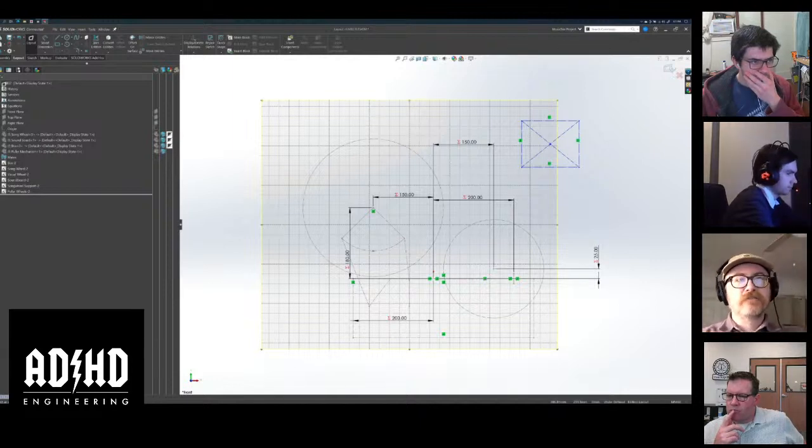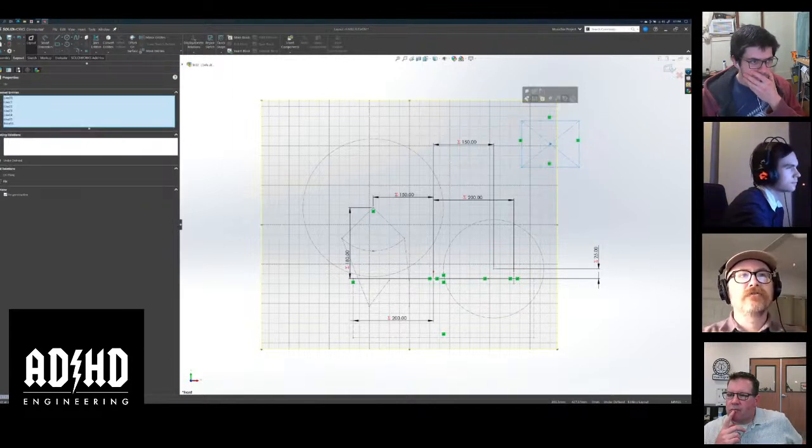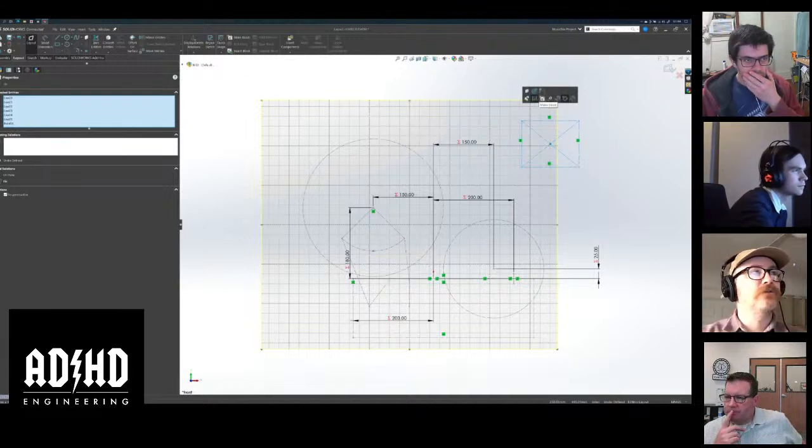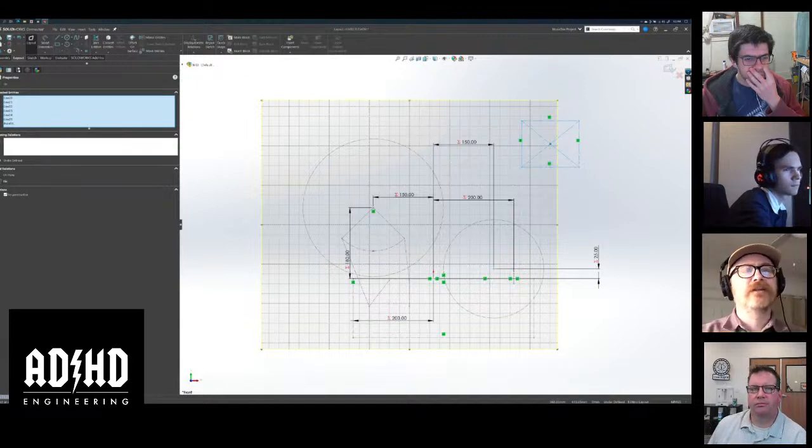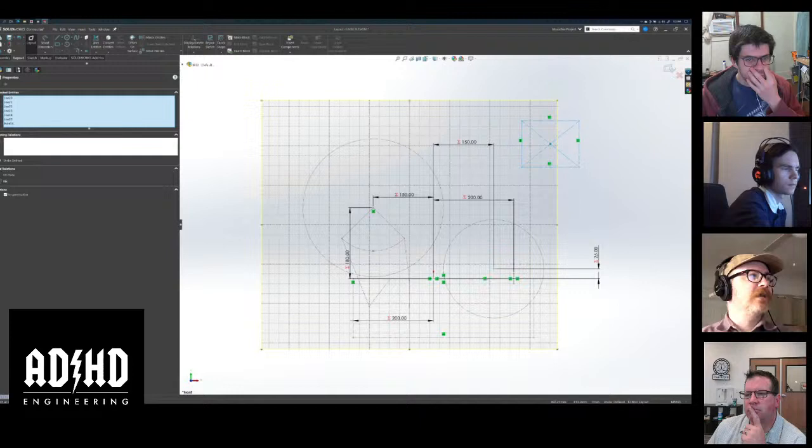But anyway, we're going to take all of these parts and turn them into a block. So select them all. And then you'll notice in this little menu, there's this guy. It says make block. We can also do it over here. That little menu disappeared as soon as I moved. But anytime you do stuff like this, whether you're selecting geometry for relationships or whatever, that little menu shows up. Anyway, we're going to make a block.